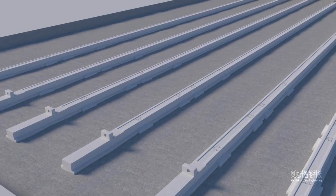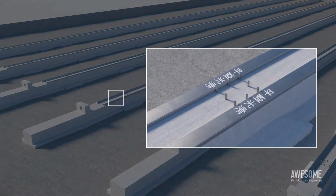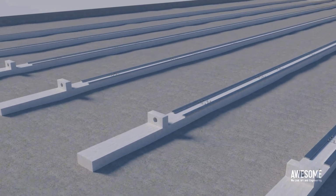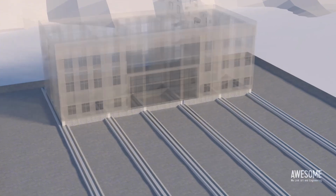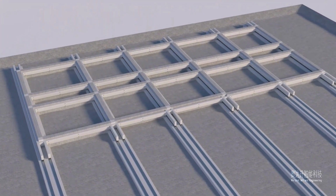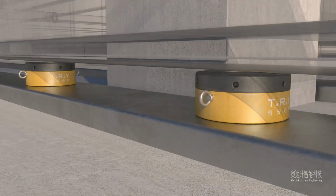Embed steel plates on the surface of the track beam. The surface of the steel plate needs to be flat and smooth. Then, backfill to a certain extent. The reinforced concrete column adopts the column holding bracket support method. The brick wall adopts the double clamp beam support method. Arrange the jacks reasonably between the upper and lower tracks.